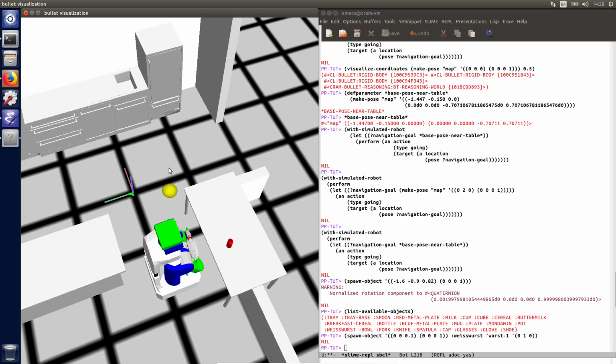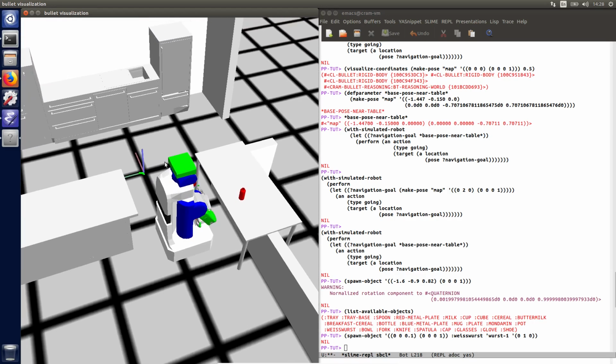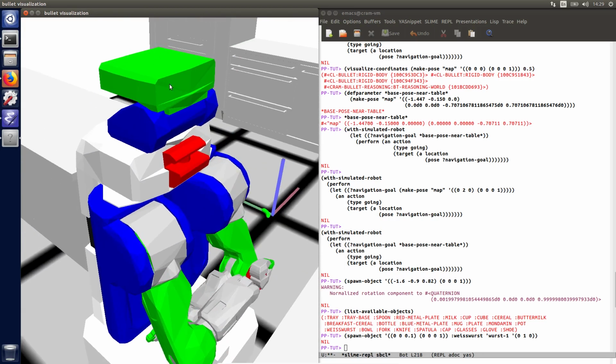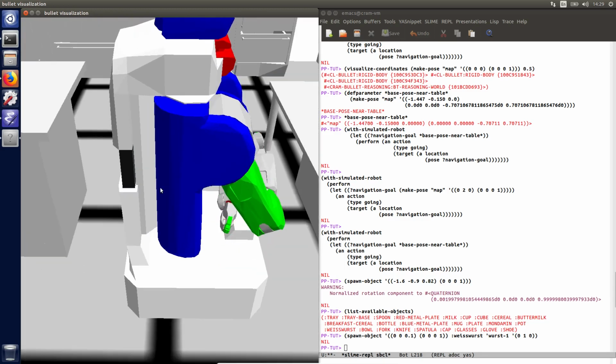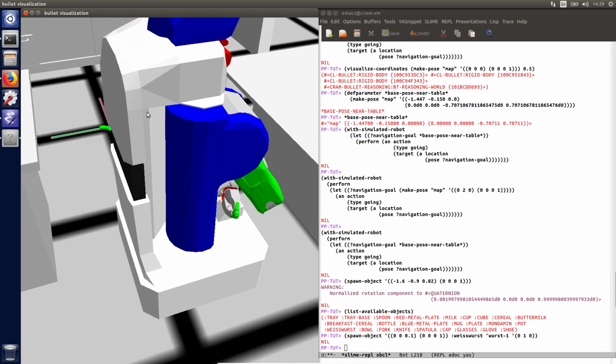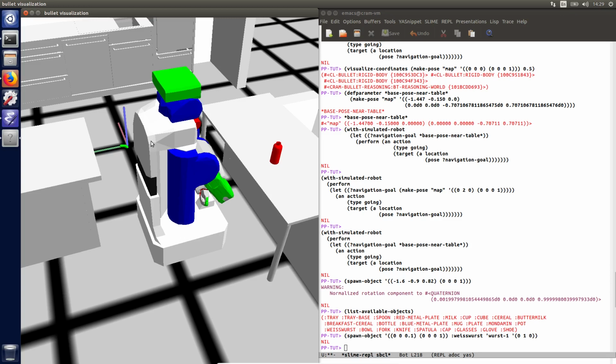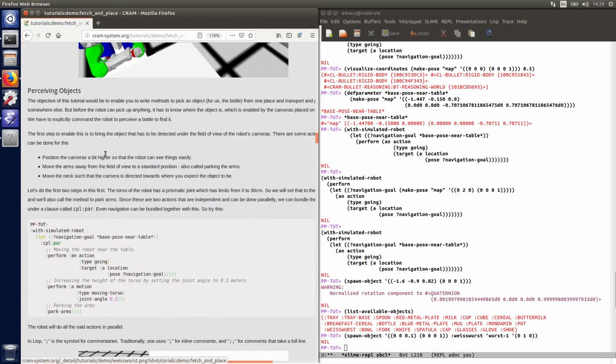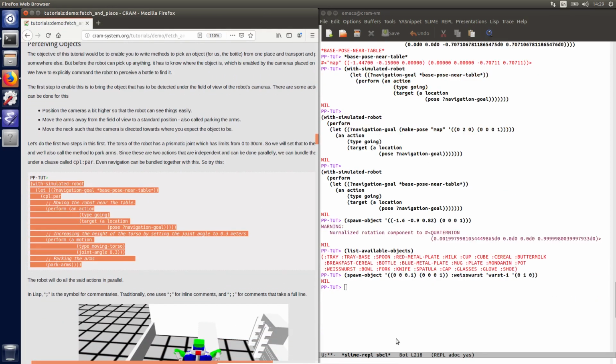The camera has to be at the appropriate height. And in human environments, it's usually best to have the robot camera at the human eye level. So the camera here in the robot is going to be located somewhere here. And our robot has a torso joint which can go up and down. So we will command our robot to go up such that his camera is at the human eye level. And finally, the arms of the robot have to be out of the way of the camera. Okay, so to do that, let's send the appropriate commands to the robot, and that's happening here.